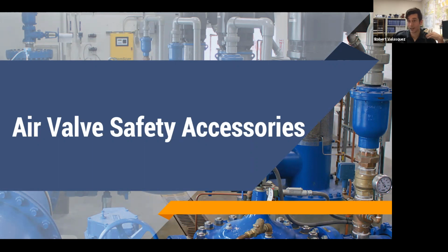Homeland Security started looking into this and saw that when you do that, you're providing access to a protected water system to the general public. So you've got this pipe that's up out of the ground and bent around. If somebody were to put water or something containing contaminants or toxins into that pipe and pump it down into it, the next time that air vacuum valve opens, it would send it right into the water supply. So we don't want to do that either.